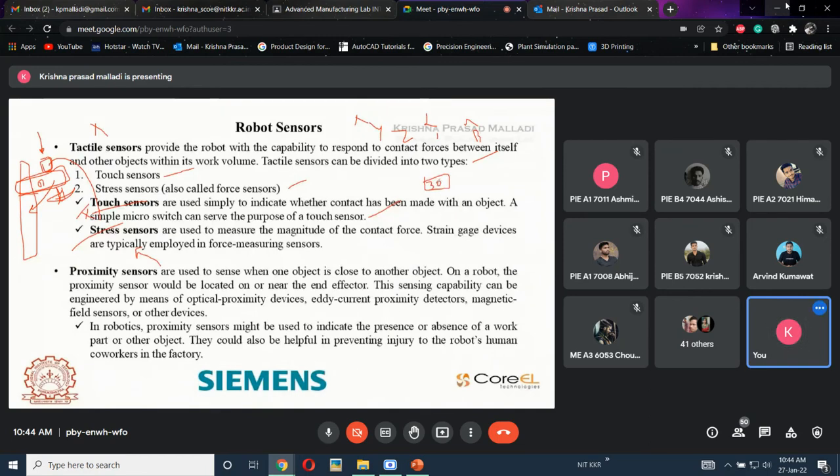Now if an additional force or additional impact is there, the robot gives feedback to the control system, where we are operating the program. There will be an error, like proximity sensor or touch sensor is enabled. If this is enabled, it means something is touching the robot, or something is provoking the robot motion.